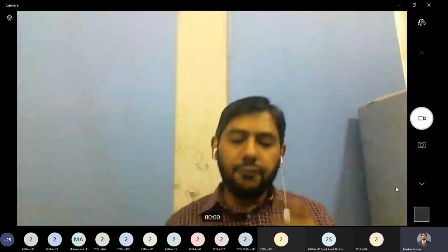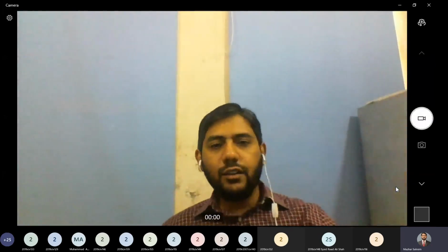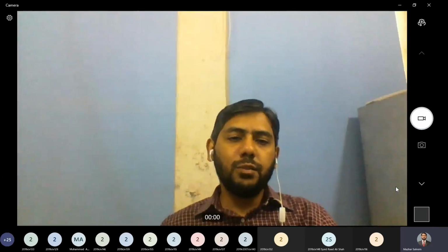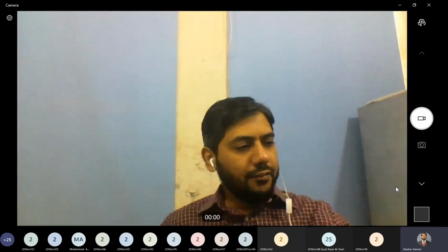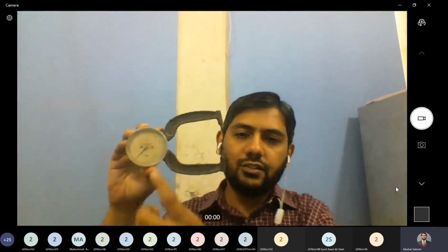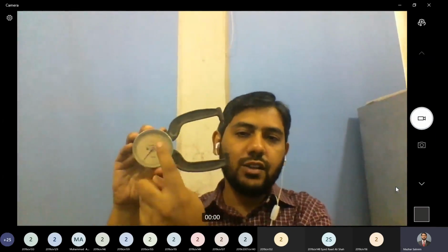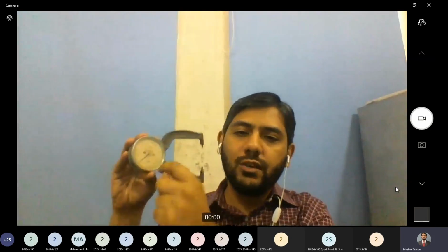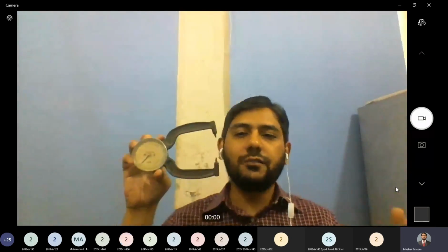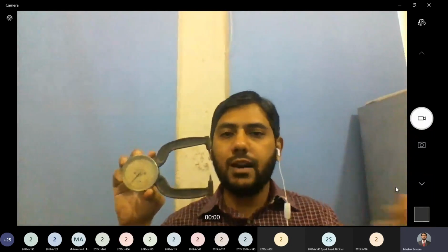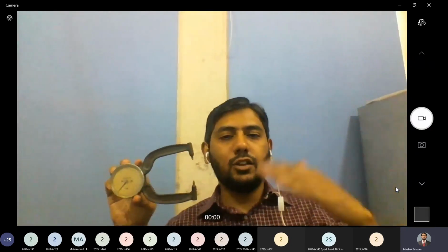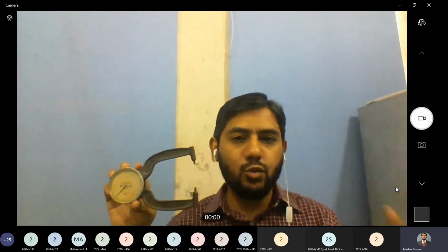So one thing that I want you to learn is that if I give you an instrument and even if the least count is not written, you should be able to judge the least count. If we know that the total range is, say, 1 inch, then you should be able to see that 1 inch is divided into 10 divisions, and those 10 divisions are further divided into 10 equal parts or 20 equal parts, and that part is further divided into, let's say, 2 equal parts.